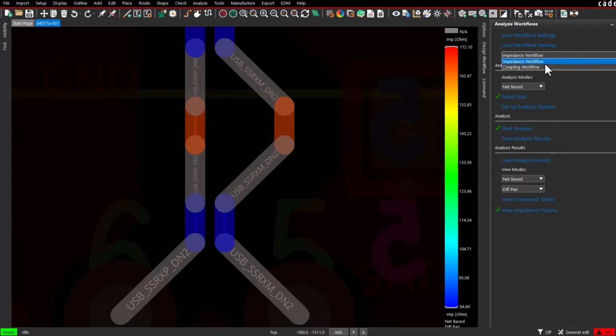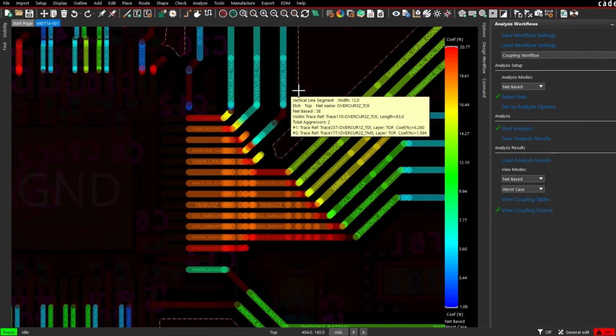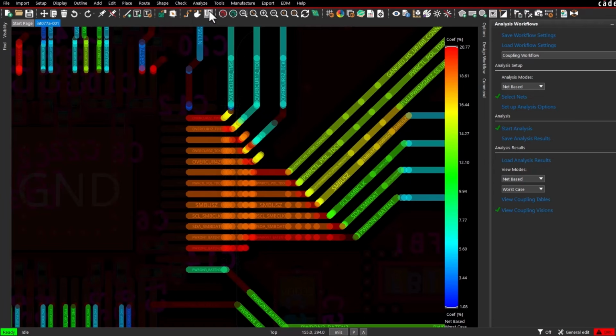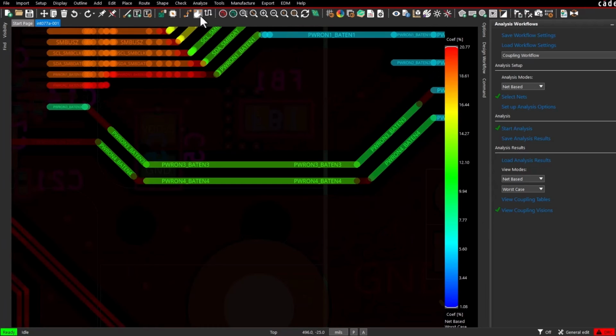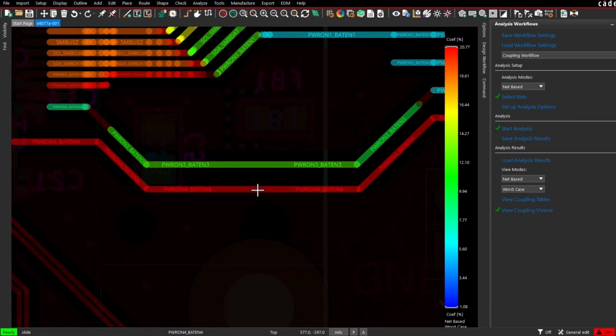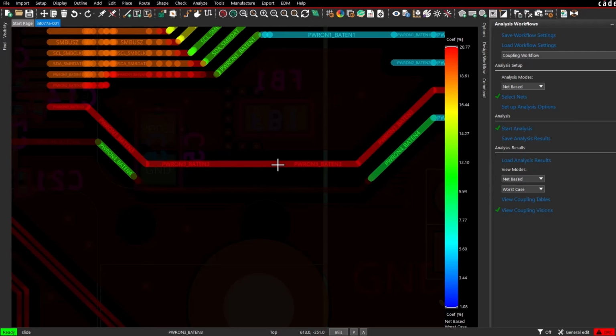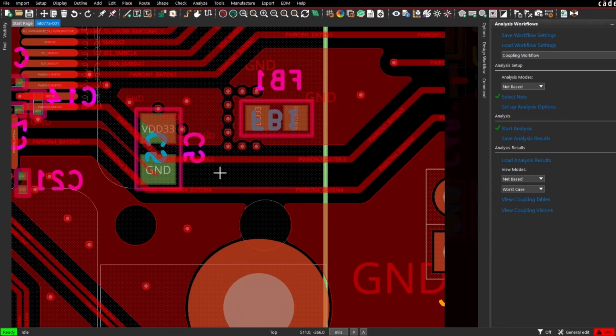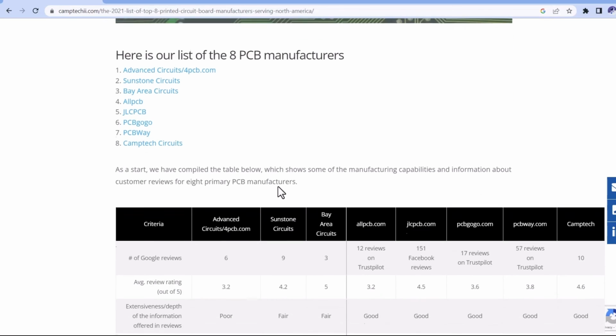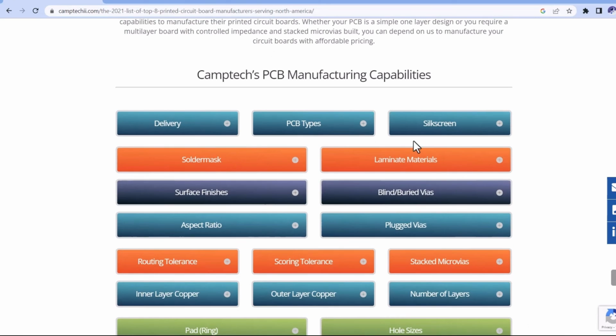Okay, once post-route analysis is done and finished, you would modify the printed circuit board and make some adjustments, or revise the board and do cleanup of the PCB, re-export the design files, and then repeat the process until you have high confidence in your simulations that the board will work. All right, then finally you would send the files to a manufacturer.